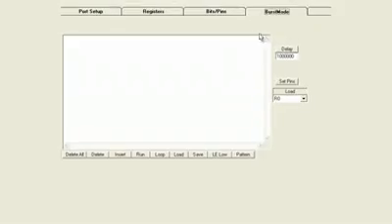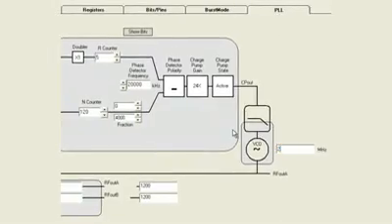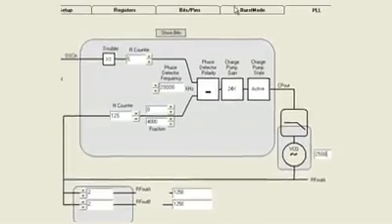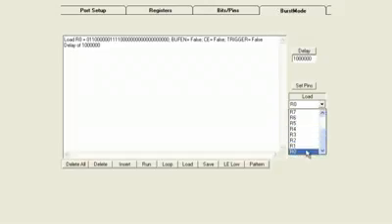On the burst mode, what we would do here is select a value here, and then pick a new frequency here. I just happen to know that the R0 register is the one that contains the frequency information, and I'd hit run. And here it's going to go back and forth between these two frequencies.